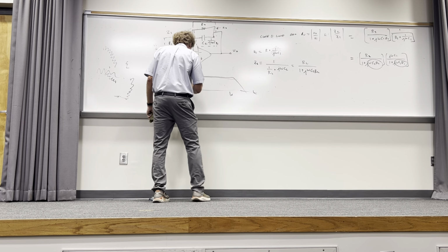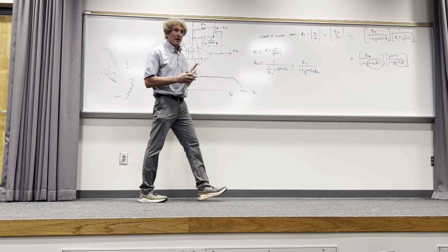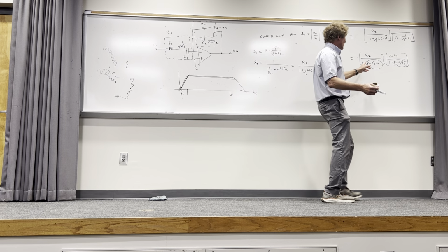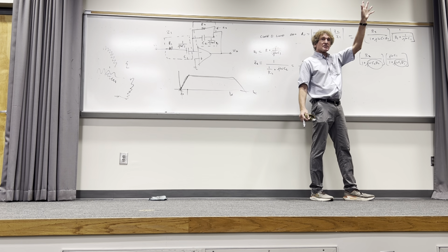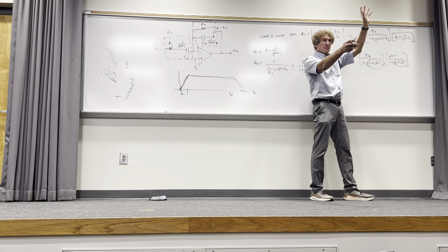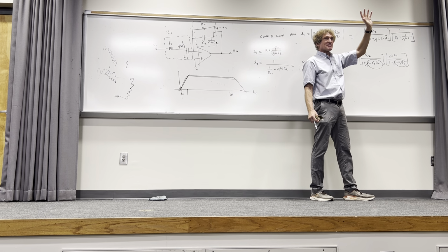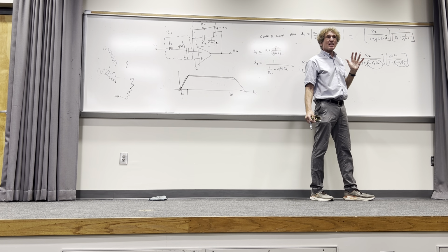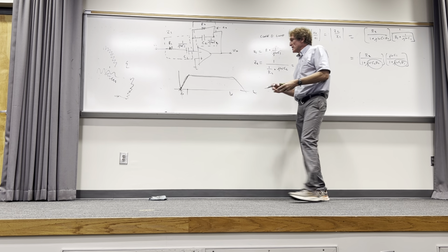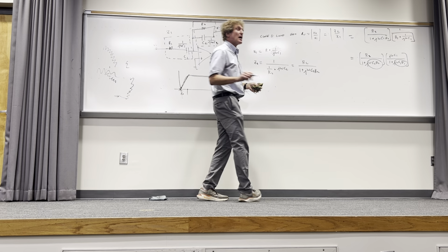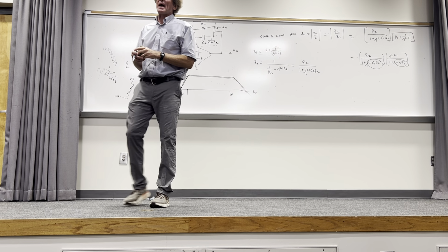We'll get this frequency in a second. Then, all of a sudden, the second one, I don't know which one it's going to be, when the second one becomes of the order 1, how many understand what I'm talking about right here? You follow me on this? Everybody with me on this? All of a sudden, it'll start going down by an additional 20 dB per decade. That's here. Everybody with me? This is called a band pass filter.